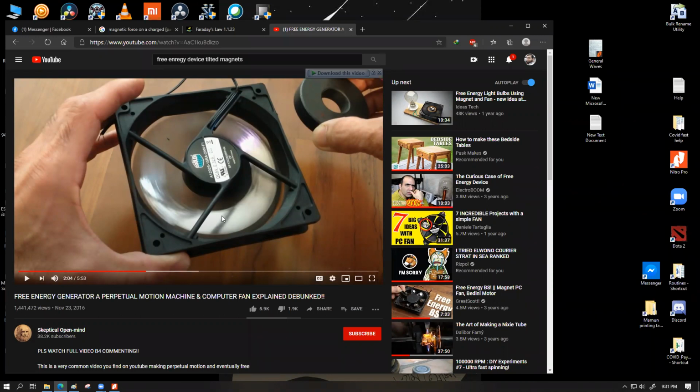They're continuously going across an alternating magnetic field orientation, which means little by little, each of their dipole arrangements is slowly becoming disturbed. Over a period of usage, all of those permanent magnets are going to slowly lose their permanent magnetism. This is not an indefinite source of energy. It is only going to work as long as those magnets have enough magnetism left to overcome the friction of the generator unit that he has at the center.